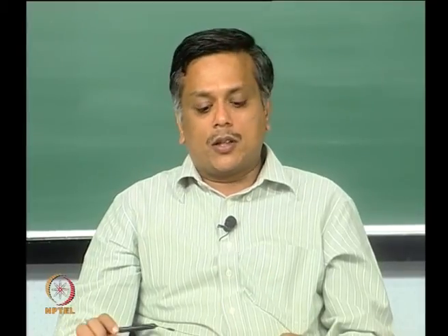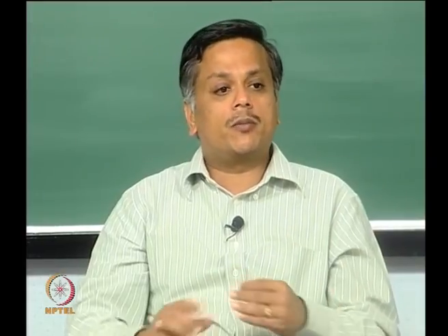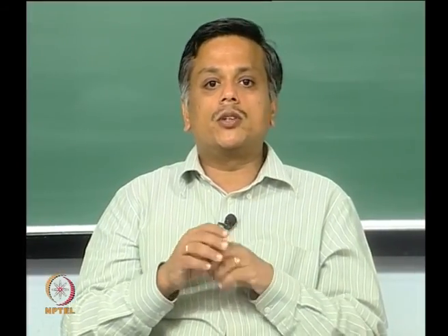Okay, just as we said, the indenter on the drop size overestimates the drop size, the mean drop size, because it is going to leave out some of the smaller drops. So, these are ways of bounding the measurement or bounding the error on the measurement, which is always a useful exercise. Okay, we will stop here.